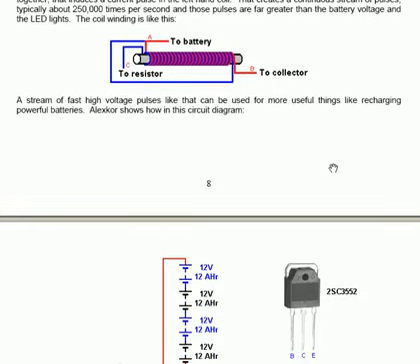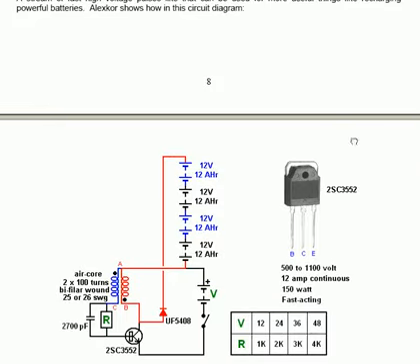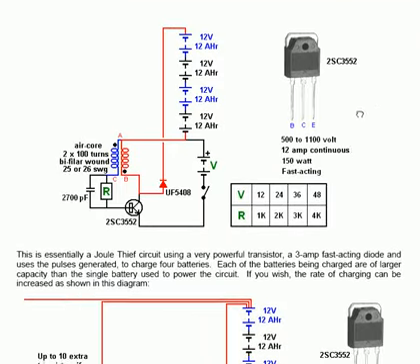Typically it's probably the white taped former shown in the earlier pictures, but those are connected to the collector of the transistor and through a resistor to the base of the transistor, and the output high voltage spikes are fed through a UF 5408 high speed 3 amp diode through to a row of 4 batteries which are connected to the plus of the drive battery.